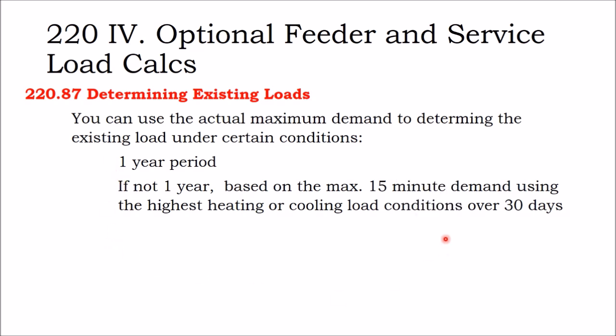Sometimes when you have a solar rebate program, in order to do your array size, they're going to look at your maximum home's load. And it might come back that your home only uses 14 kilowatts of power, and so you can only have a 14 kilowatt array on your rooftop. And you say, well, wait a minute, I have a 48 kilowatt electric service panel. And they'll say, well, your demand never gets that high. And you can say, well, hold on a second. And you go and you turn on all the appliances in your home, and your demand will surge up to 40, 45 kilowatts. And so I want to do the largest array I possibly can.